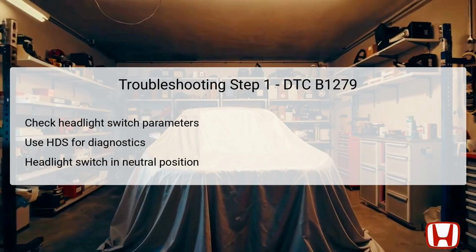Once positioned correctly, assess the current conditions and values related to the headlight switch, focusing particularly on the high beam and passing functions. If either of the information indicators illuminates during this diagnostic check, it indicates that there is potentially a deeper issue requiring further investigation. If they do not light up, you will proceed to the next step in the troubleshooting process to determine the cause of the malfunction.